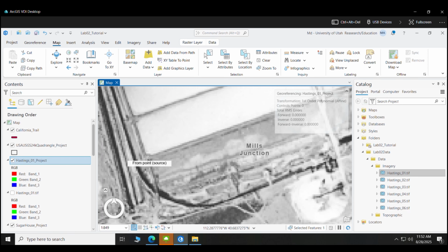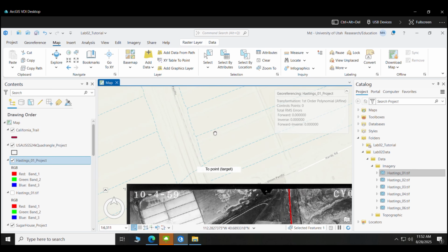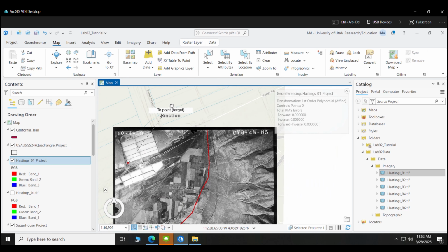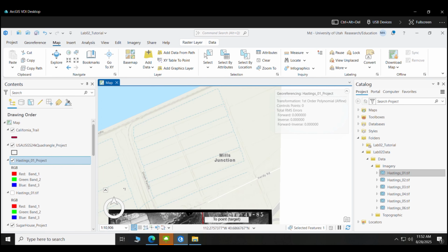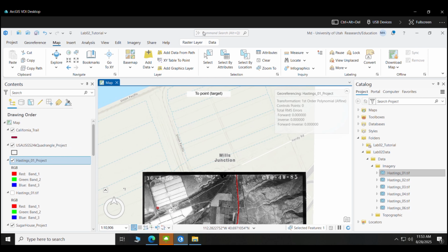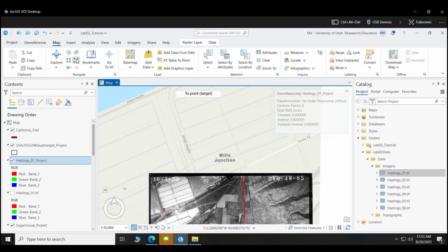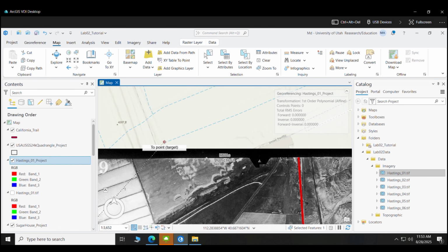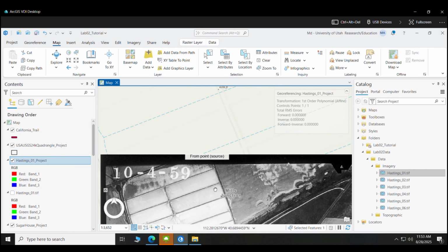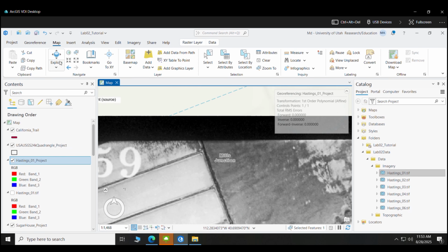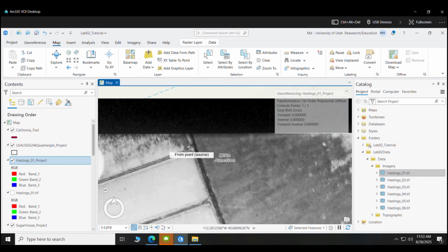So when we are done with the projection, we will do the georeferencing, but this time we don't have grid lines to follow. We will see several features or roads from here. You can see that this point of the image corresponds with this point of the topographic map. That's why we are trying to add a control point here and give the other control, the target point, to be here. Now you can see that the satellite image has been located in its perfect location.